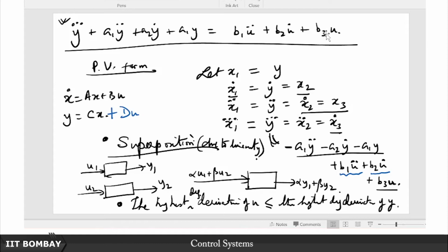So all that idea about having to draw that block diagram, then call that output of the op amp, that might have some physical significance. That might tell you something about the so-called memory of the system that is being conveyed or carried forward by this state, right. Everything that has happened to this system up until the instant t0 is carried as if embedded within those initial conditions, right. So that is why that has a physical significance.